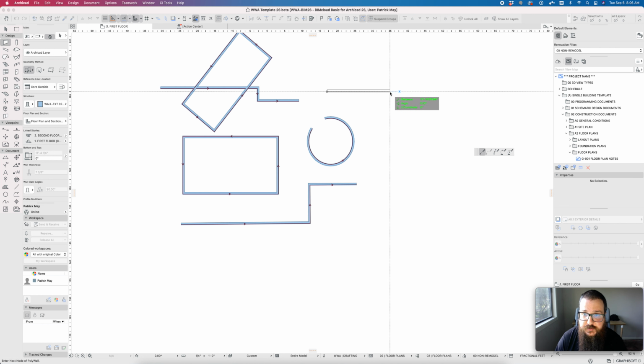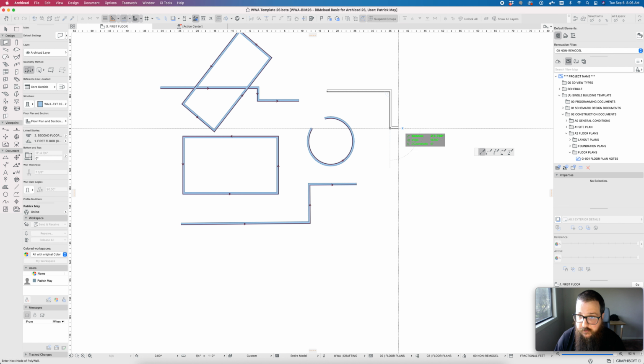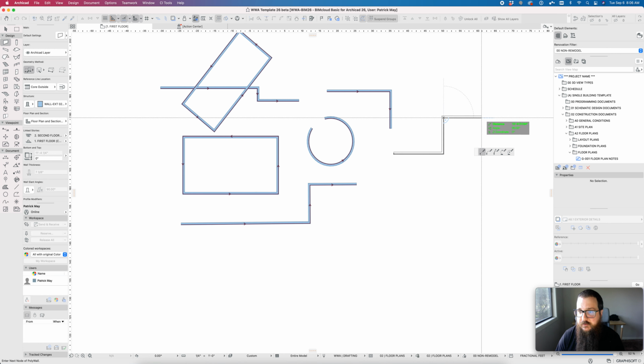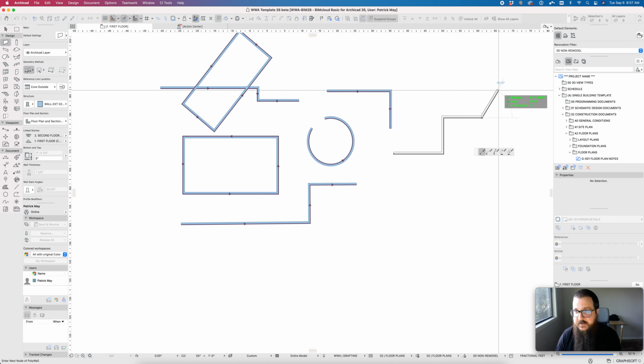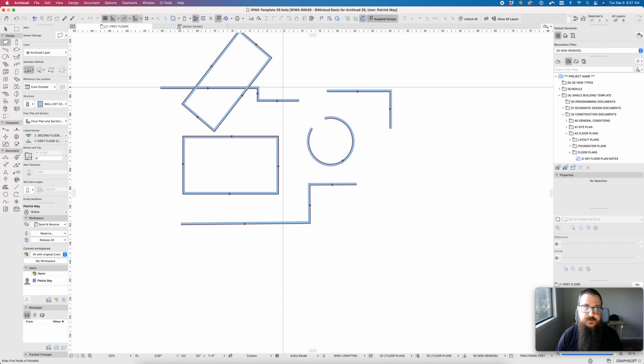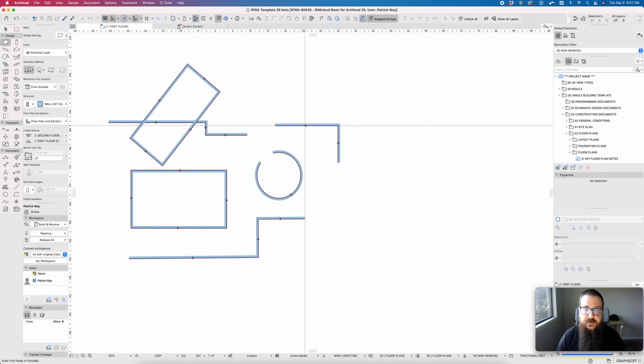If you want to place segments, you just hold Shift, type R, that gives the radial distance, and you type in the length of that wall segment. When you're done placing segments, you just click on the end of the wall. If you find yourself placing multiple segments and you get a segment that's off, if you hit delete, it'll deselect that segment and you can then proceed to place it again. If you hit escape, you start over from scratch. So that's a few quick bits of information on placing walls.